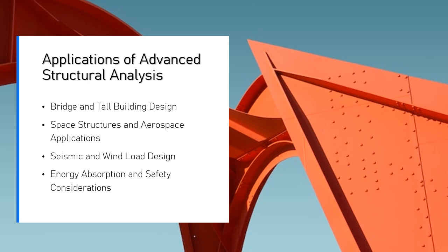Advanced analysis. Response spectrum analysis, time history analysis, and linear/nonlinear dynamic analysis are commonly used methods to assess the structural response to seismic loads. Engineers model dynamic behavior using finite element analysis, FEA, software such as ANSYS or SAP2000 to simulate earthquake-induced vibrations and displacements.